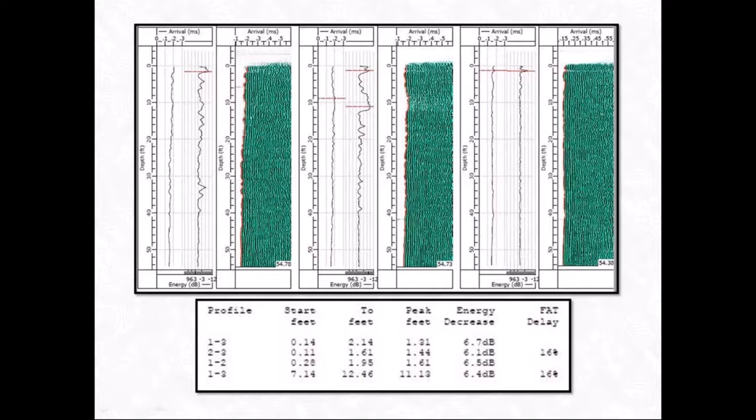And here's some data. So you can see the arrival times. This is a waterfall diagram, which is very helpful. So you like to see consistency in this. So this is an indication that the concrete quality between the transmitter and receiver is uniform throughout the length of the shaft.